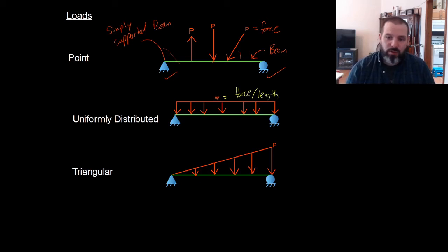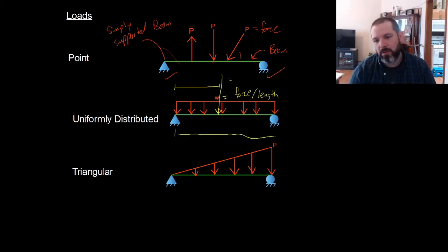Now, in order for us to do any type of analysis with this uniform load, we need to find the resultant of the force. So for a rectangular load, the resultant occurs in the middle and is equal to W times L.